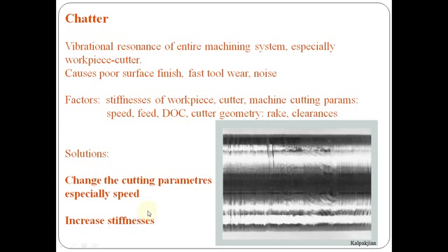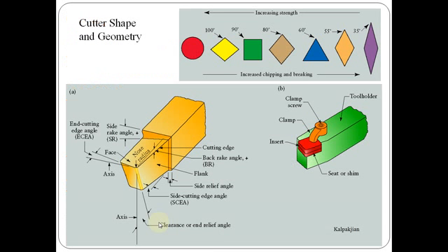The solution will be that we are supposed to control the cutting parameters, especially the speed, and we are supposed to increase the stiffness to enable effective quality machining.